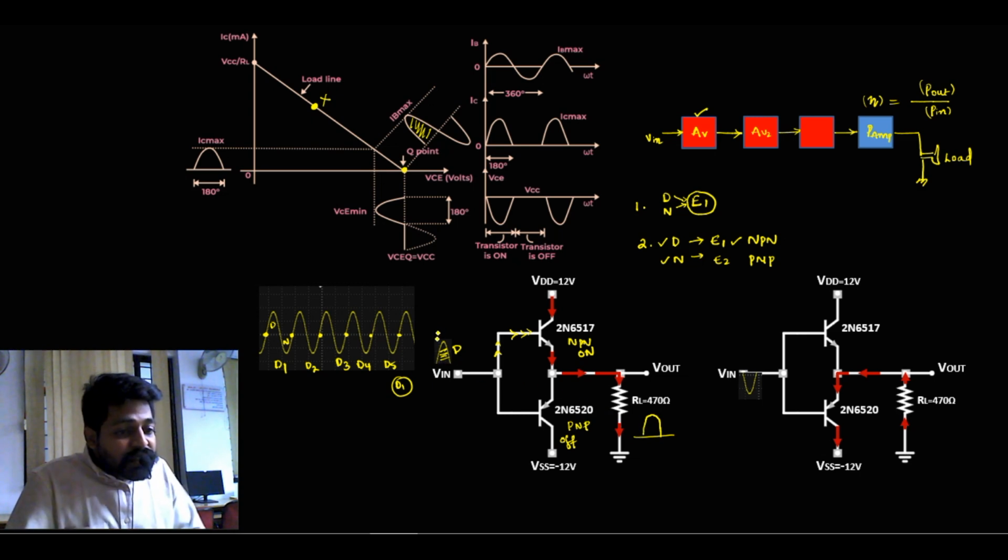When I give an input voltage over here, it will conduct a positive half cycle current. Beta times IB, where it is considered as IB, will be conducted as the collector current. So beta times IB current will be conducted over here, meaning a similar kind of signal, because it is a current controlled current device. As you increase the current, the increased current will be flowing. Decrease the current, the decreased current will be flowing.